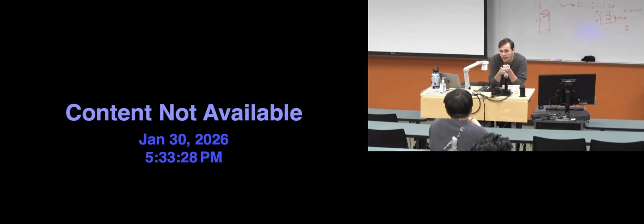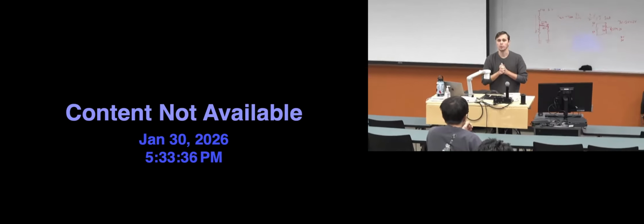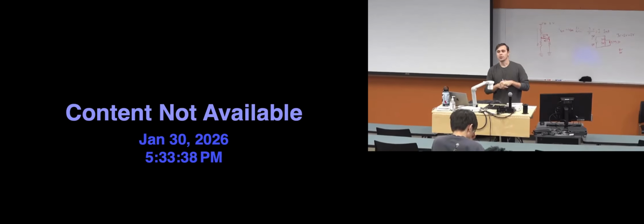We probably won't ask you to make a circuit with a capacitor, but you should know what they're used for, right? For smoothing stuff out. You remember in homework 1 where you had the circuit and it was switching the output super fast with the switch, and then we told you to add the capacitor, and you saw how it was switching slower because the capacitor had to charge and discharge, right? You should know what adding a capacitor to the circuit would do, something like that.